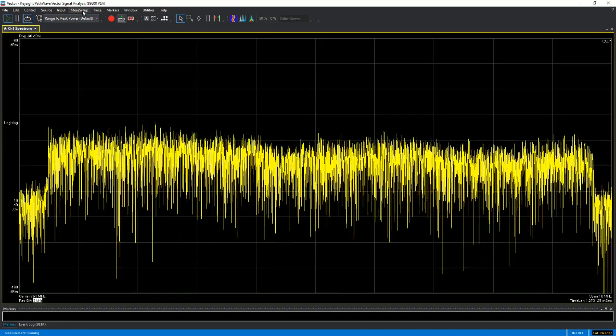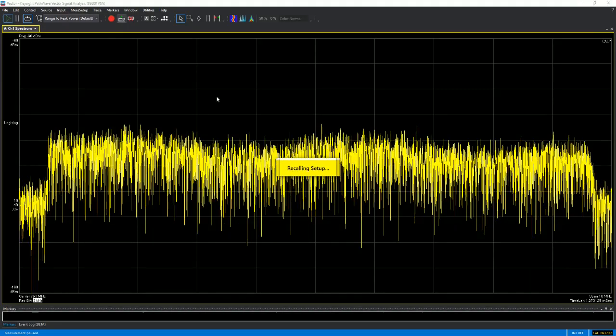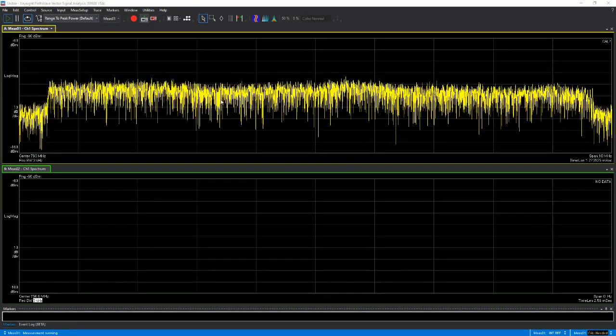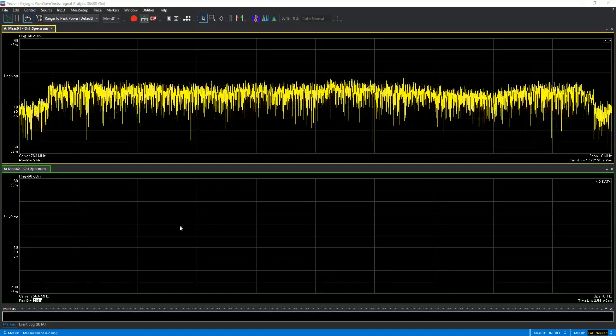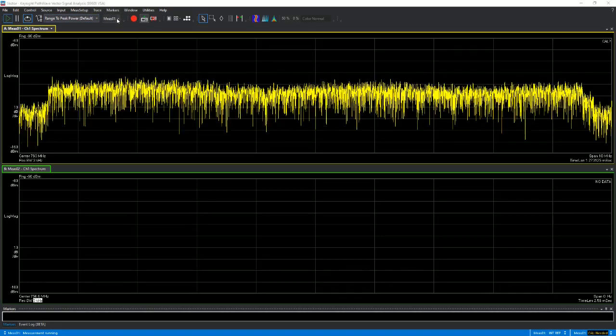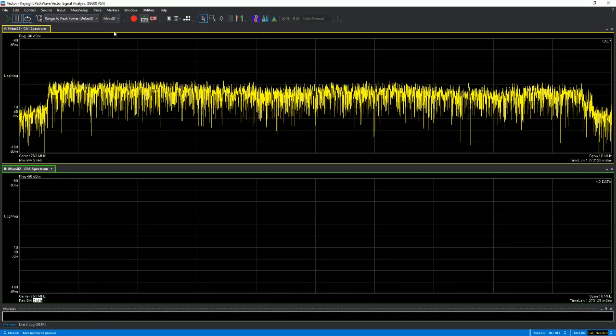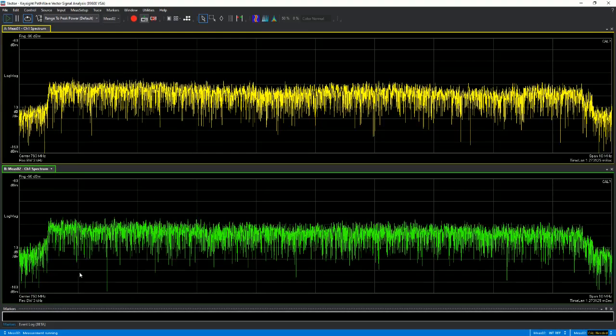Let's add on another measurement. Let's go to here, duplicate this one. As you can see, there's one active measurement and one dormant measurement. So how do we change that? Go to here, change to measurement 2. You can only change that when it's up and running. So you change to measurement 2, then you click play. So this will become the active, and this will become the dormant.